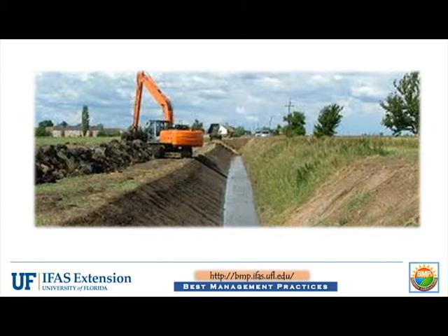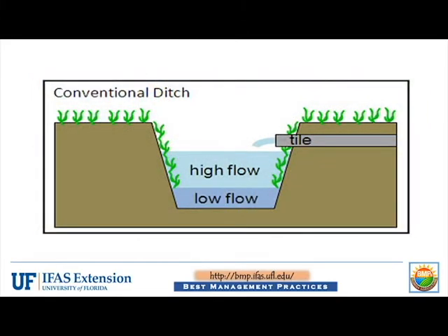Control of water table is achieved via the construction of evenly spaced ditches in addition to the beds. The use of drain tiles may be employed, particularly in problem areas resulting from general non-uniformity of soils. However, some growers routinely install drain tile to control the water table. A survey will also help determine if leveling of the land is required. Open ditches and water furrows may be required to remove the bulk of surface water. Drains should be installed in the direction of greatest slope.